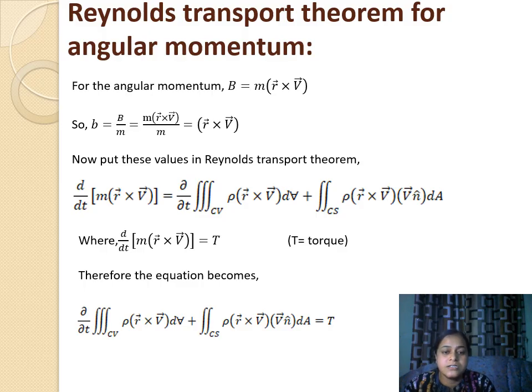Therefore the equation becomes del by del t triple integration at control volume rho r bar V bar d-volume plus double integration at control surface rho r bar V bar dot n cap dA equals torque.